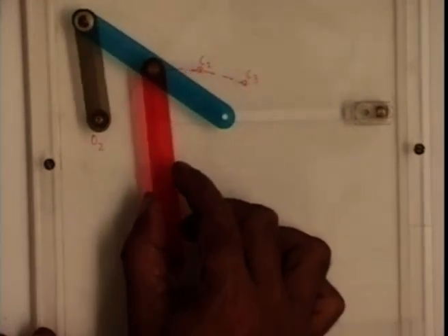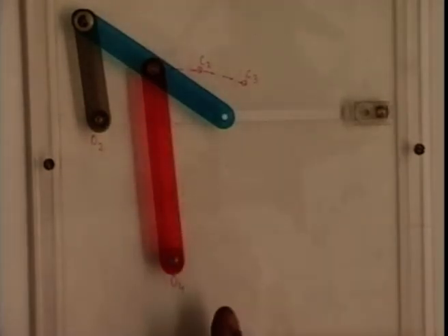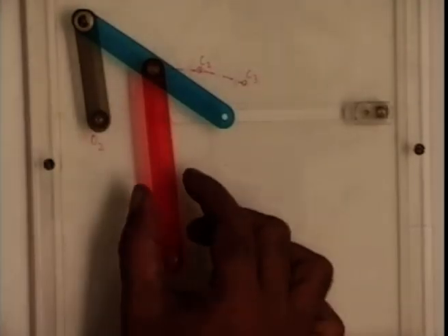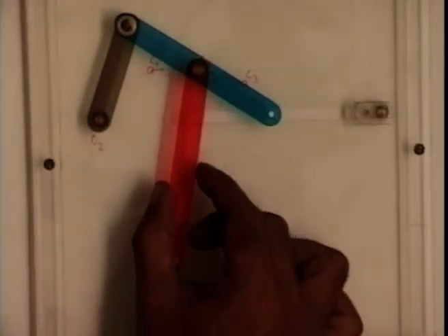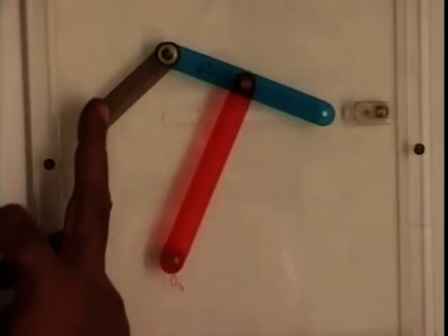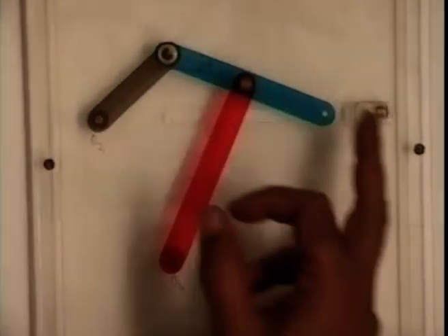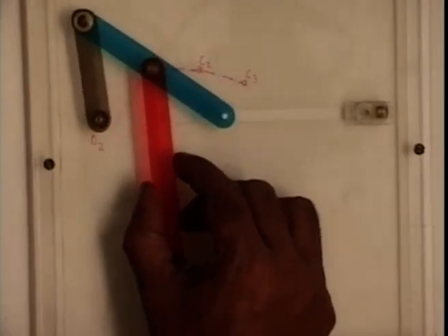So we have generated a coupler curve synthesis problem or path generation problem coordinated with the input movement. As it goes from position 1 to position 2, this rotates by a specified amount. As it goes from position 2 to position 3, again it rotates by the specified amount, which was dictated by the original slider crank. So this is what we call a two-stage synthesis.